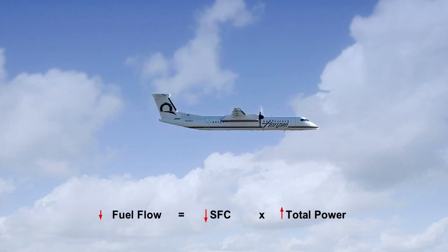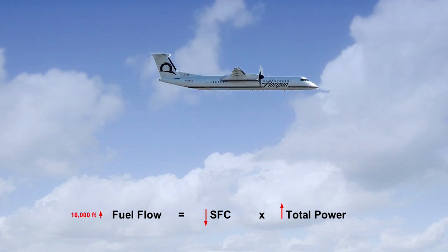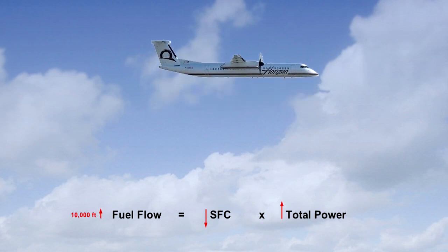Turbopropeller aeroplanes function in a similar way to a jet, since they are, in essence, jet engines with a propeller attached to a geared shaft. However, even though the turbopropeller engine gains efficiency with altitude, the power required increases, offsetting the efficiency gains. This means that for the majority of modern turbopropeller aeroplanes, maximum endurance is achieved at around 10,000 feet or less.